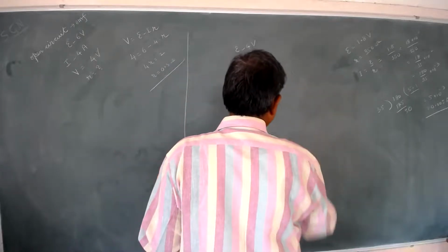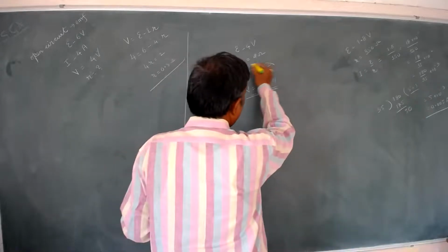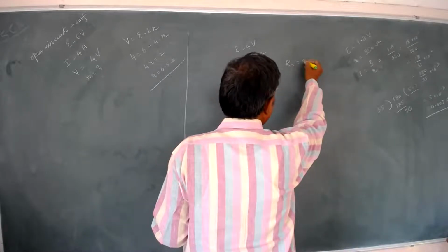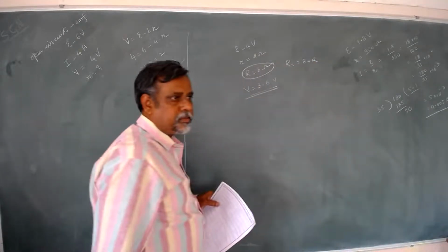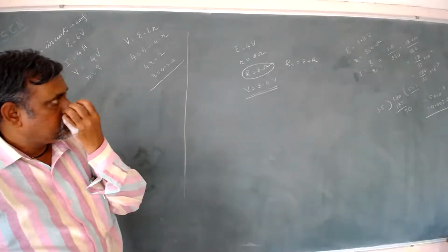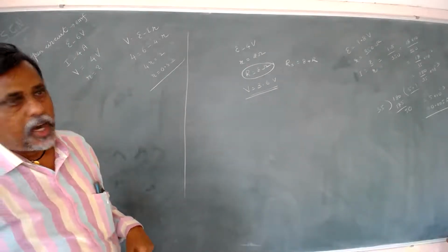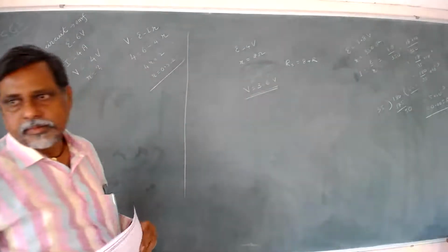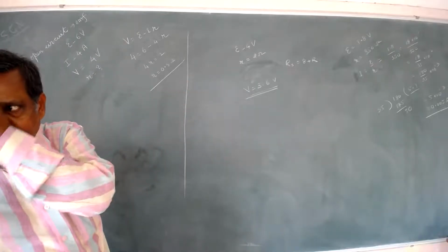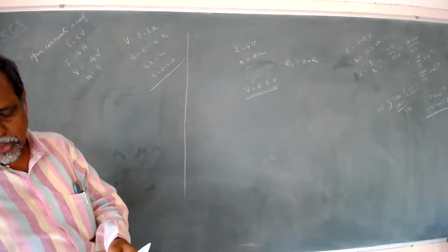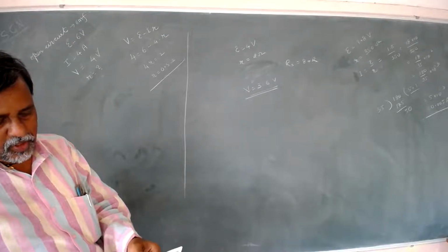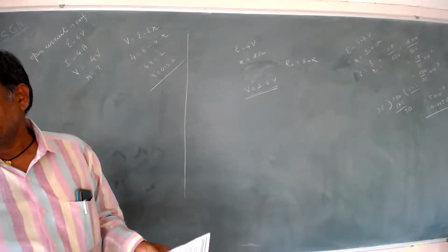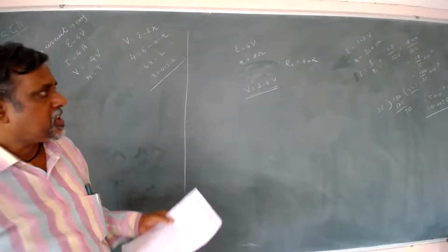So to have this 3.6, this alone should not be taken. Some additional R should be taken. RS is 8 plus R. Understood? R means not this 8 ohm. Did you understand that? Some additional resistance, so you need to connect in series, R1 plus R. Yes or no?